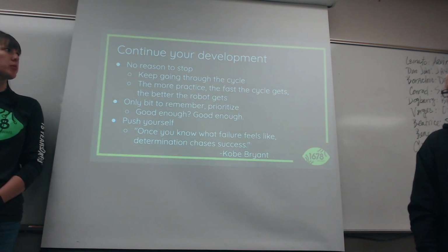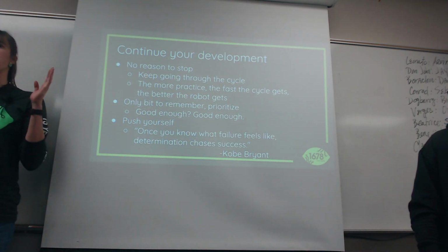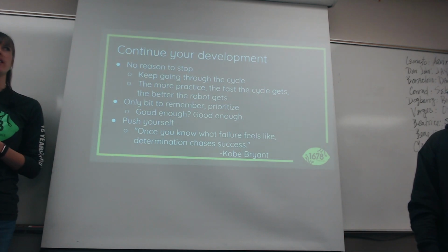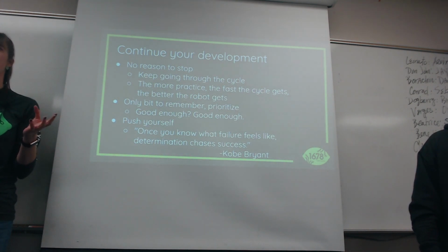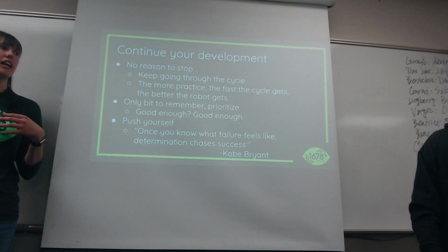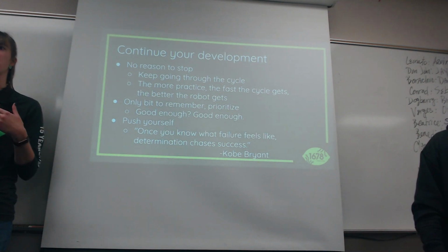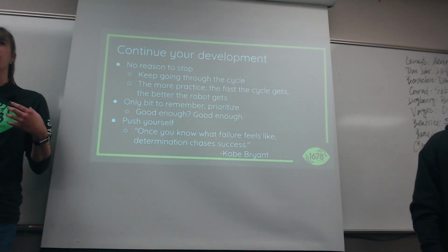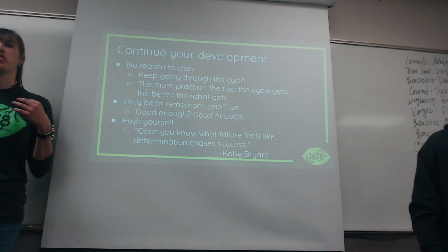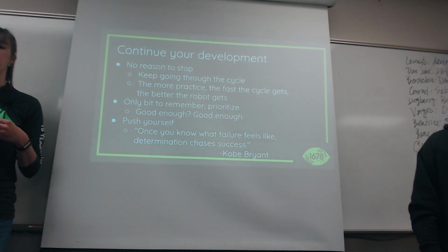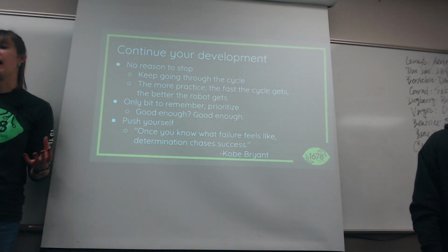Yeah, one of the examples of something that we did keep improving after we had our whole structure, it was noticed that the sensor that was picking up the red and blue sometimes would false read a color. So we spent time adding more lights, designing in tweaks so that the sensor could better detect and not shoot out the wrong color ball. So that is something that's going to improve your performance, right? Because you're going to more consistently pick out the right color ball, versus something like Brendan mentioned where it's just a nice to have.